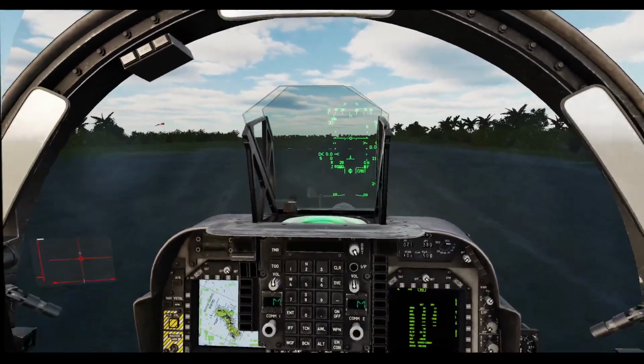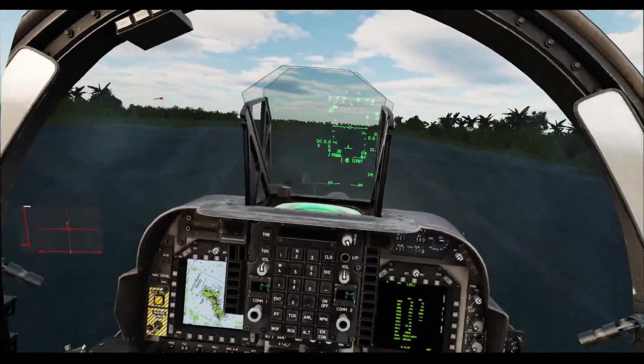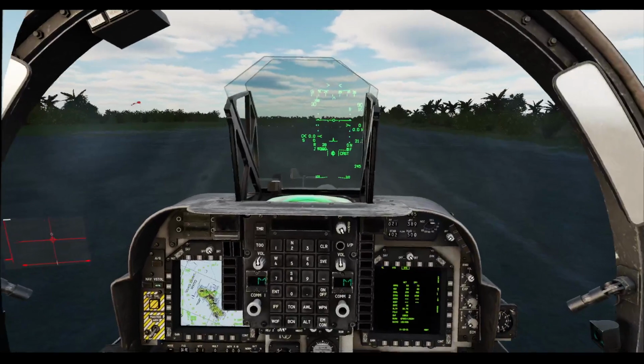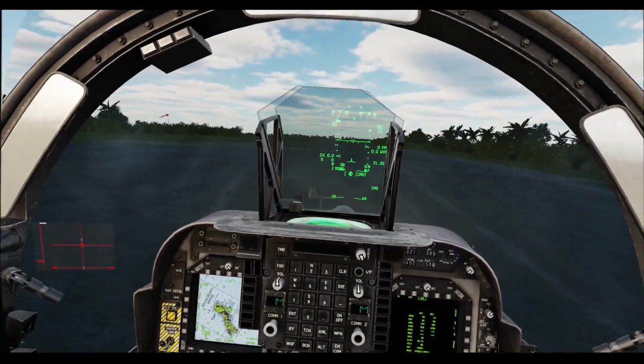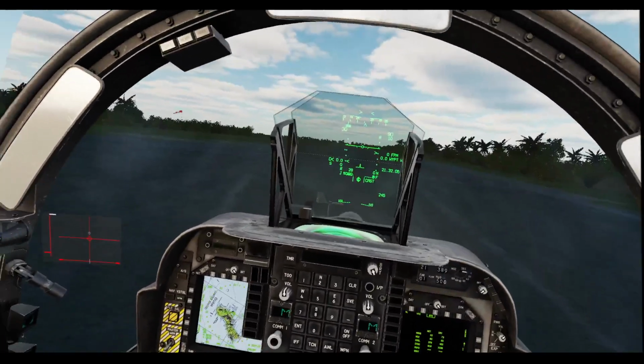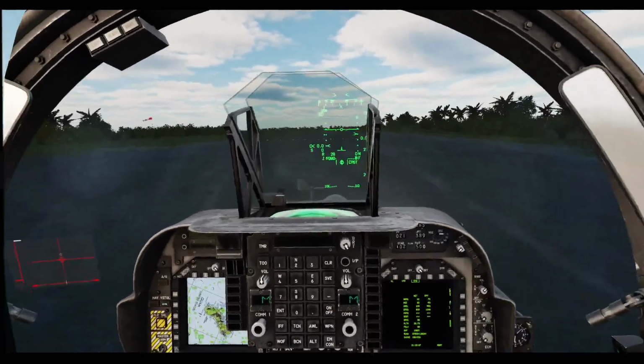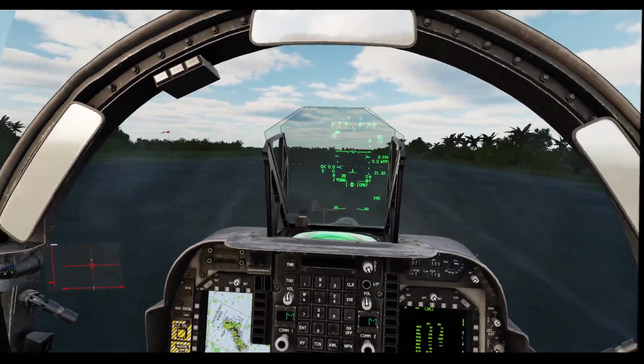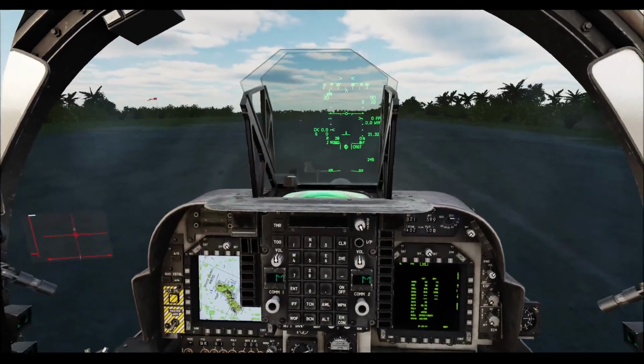However, if you're operating from a larger airfield, you might bring the nozzles all the way to 0, as well as bringing the gear and flaps up as normal for the accelerating transition. That's just because if you've got a long runway, you don't want to be doing 180 knots the entire way because you go into conflict with other jets in the circuit, so you want to get up to 250 knots as quickly as possible.